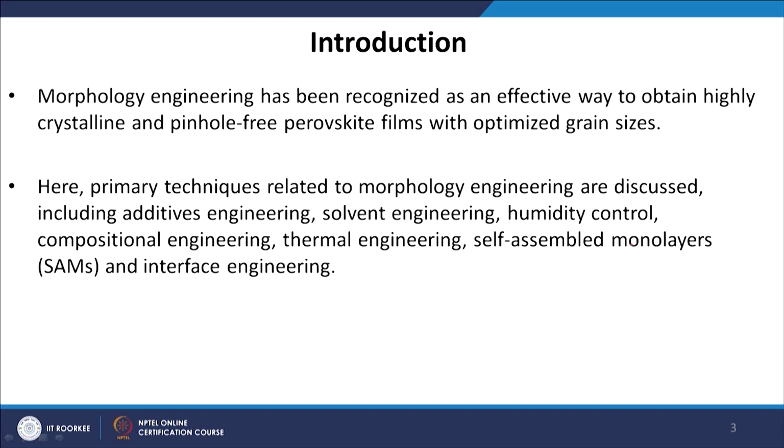Now morphology engineering has been recognized as an effective way to obtain highly crystalline and pinhole free perovskite film with optimum grain size. Here primary techniques related to morphology engineering are discussed, introducing additive engineering, solvent engineering, humidity control, compositional engineering, thermal engineering, self assembled monolayer and interface engineering. Let us look at this chart.